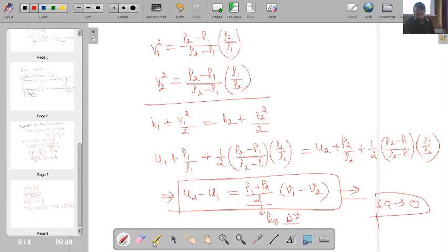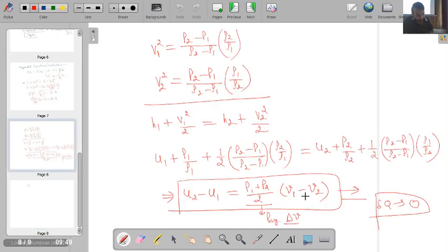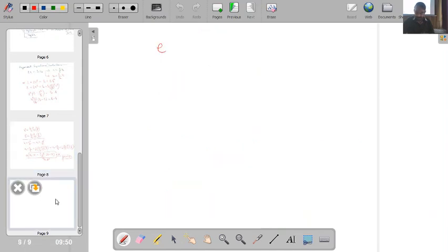Another important point is, when we go with thermodynamics, we know that for a simple compressible substance, to designate the state of the system, I require two independent intensive properties. So I can say that if I know the pressure and specific volume, because that is something which is involved over here in this equation, then I can predict its internal energy.